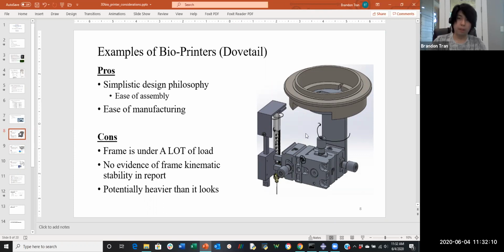And then there are some instances of a potential change in angle happening as this thing is activated. So with the kinematics involved, regardless of whether this thing can handle its shear or not, which was already calculated to be able to handle the loads being applied to it, kinematically it won't serve a good purpose. You want things to be stable in their designated position. If this thing is turning, you're going to be off by some positions. And if you want finer quality, that might not be the best thing to use as a support.